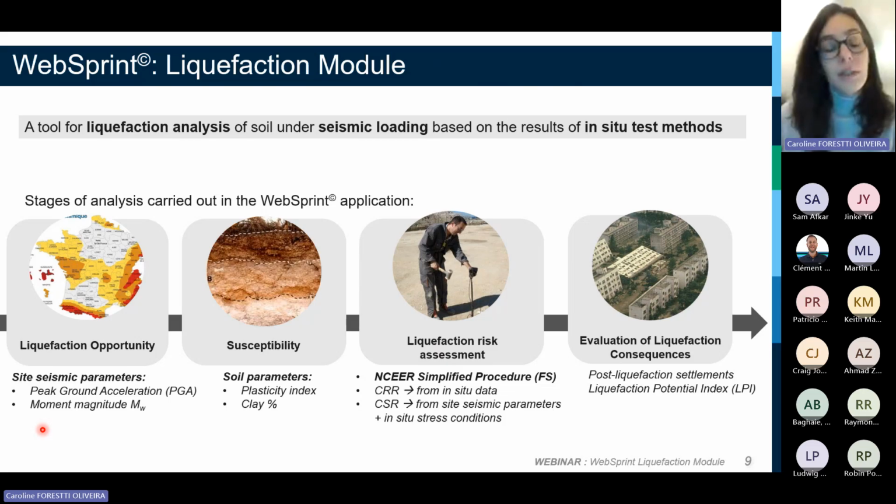So you take historical data, and you know what kind of earthquake can occur, the intensity, the solicitation, and so on. This is important because if you're dealing with a site that's not seismic at all, the chances of getting liquefaction, or this kind of instability, are pretty low. So these types of sites are sometimes not considered; we don't do this kind of verification.